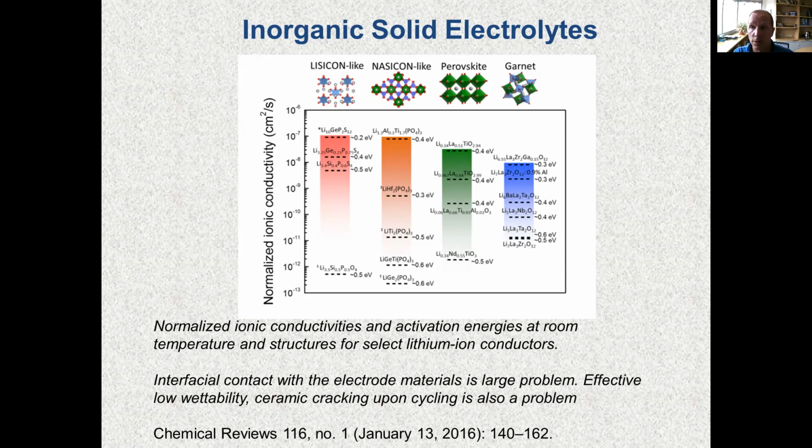I mentioned this is a real significant problem with silicon anodes because silicon undergoes a 300% volumetric expansion and contraction. But even in the case of the lithium cobalt oxide and the graphite, we have 5 or 10% volumetric changes of the materials upon lithiation and delithiation. In a liquid electrolyte formulation, these small volumetric changes are not really a problem. They don't really cause any issues.